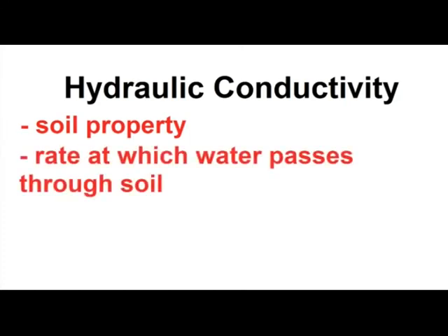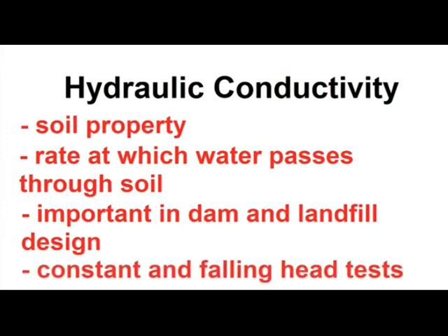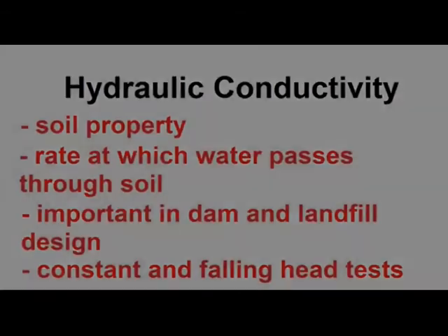It is important to be able to know how to measure hydraulic conductivity, as it is a factor in applications like dam and landfill design. There are two types of hydraulic conductivity tests: the constant head test for coarse-grained soil like sand and gravel, and the falling head test for fine-grained soil like silt and clay.